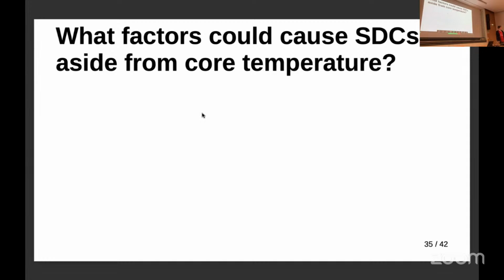I think you mentioned temperature and frequency before, if those could affect stuff, but maybe I don't know how realistic this is, maybe mechanical. There could be mechanical impact, for example, through vibrations on the main board, maybe from the cooling system. That's actually something I hadn't considered, but that's definitely something that could be an issue. We have frequency and temperature, and maybe some kind of thermal expansion.